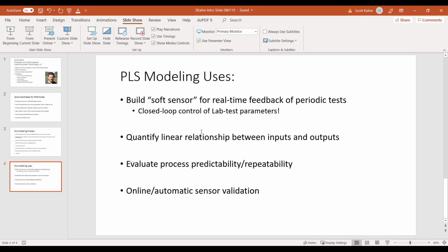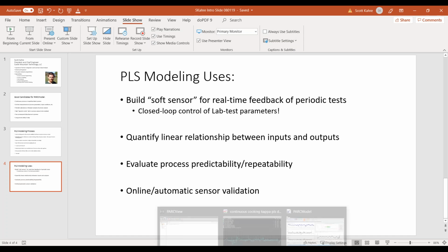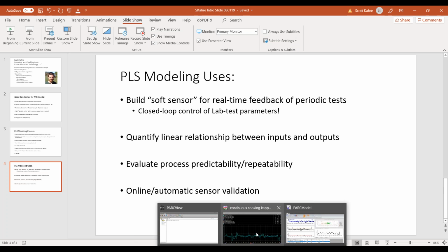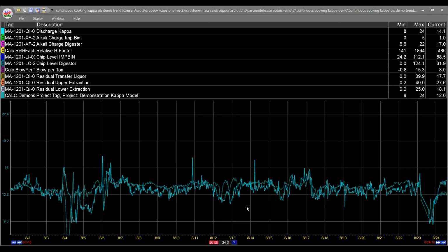The first one I had is, when you built that model, you're looking at about 20 days of data. Do you have any recommendation on what frequency of data someone would need to build this model, and what kind of time period they would need to effectively build a model? Any kind of best practices there? In my experience, it really depends on the number of output data samples that you have. So let's say that you're modeling something that's only sampled, say, twice a shift, once every 4 or 6 hours or something.